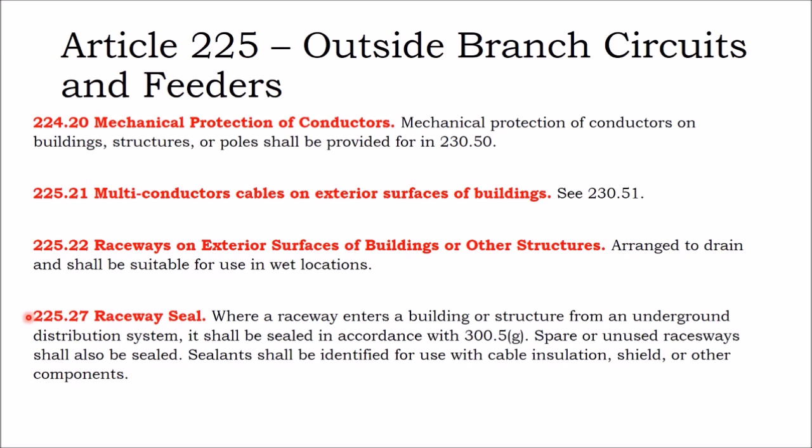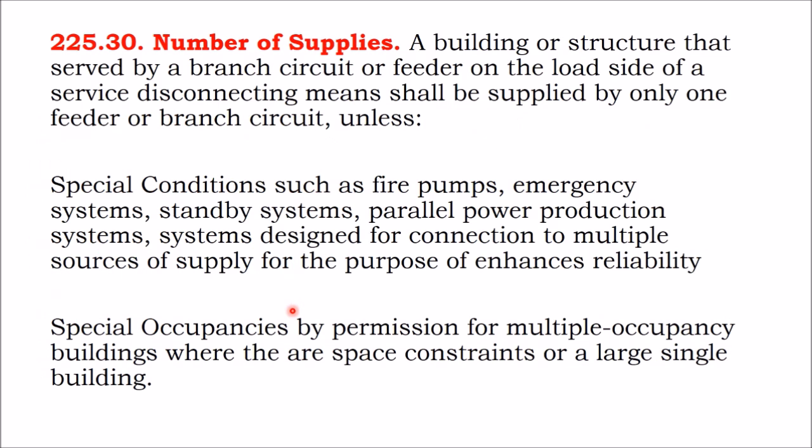So what we had to do is not only drain a little weep hole into the box, but then we also had to seal up the conduit to stop the condensation. Wherever there's a temperature differential, from the roof to the attic, from the outside to the inside, you need to seal the insides of the conduit. Conduit is not designed for you to put wire into and then pull the wire out of, and for you to put the wire back into it.